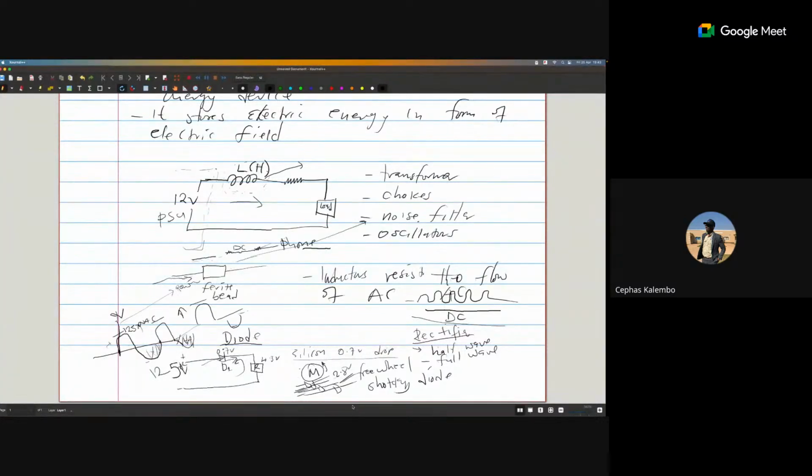Now you say, as an engineer who is designing this solar panel, we are going to say no. So what I want to do is, even if there's a problem with this, I want to be able to bypass so that this doesn't affect. So I'm going to bring here that, and I'm going to put a diode. That. This is the isolation we are talking about.